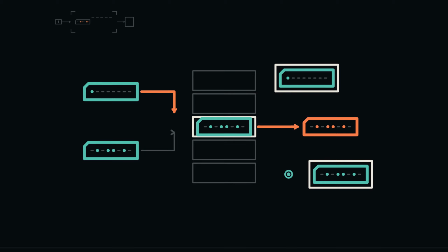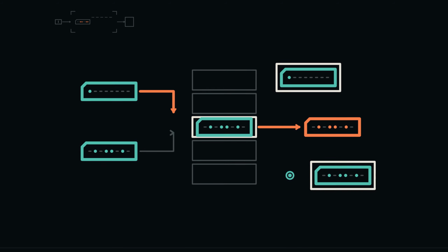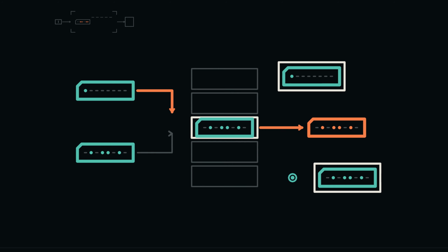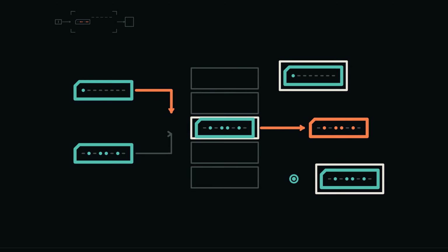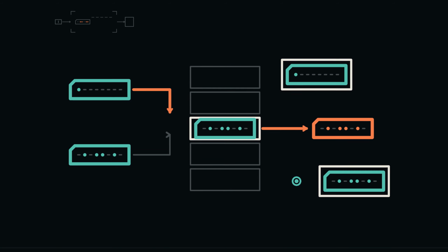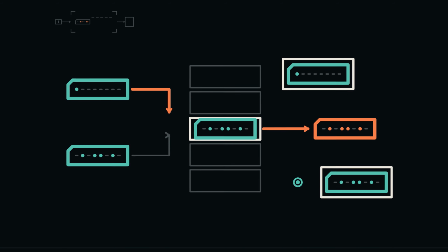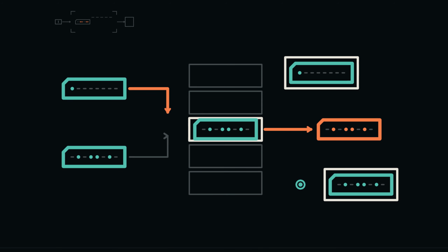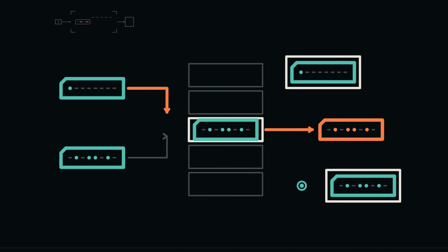Begin a separate read of address 80. If MAR does not already hold the address, the controller captures 80 there first. During the read action, the decoder selects row 80, and the memory output establishes physical conditions representing its stored byte, now 5A. MDR is selected to receive. At the read capture edge, MDR captures 5A.